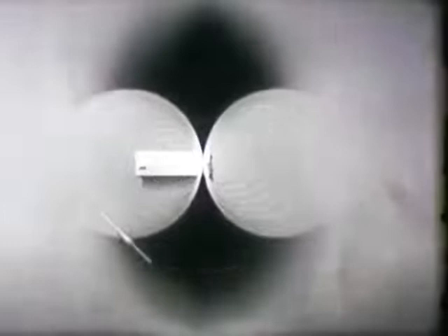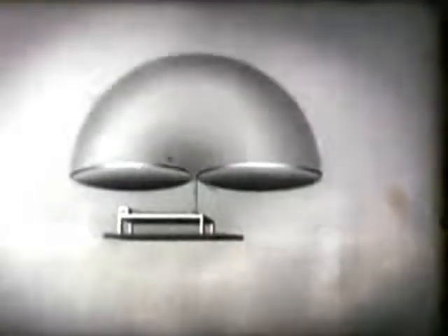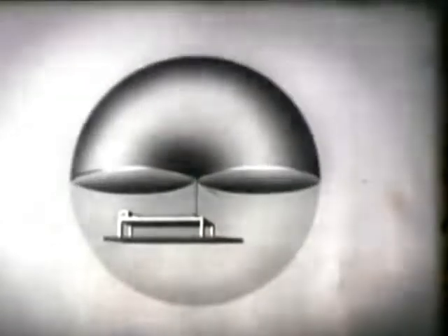Moving the receiving antenna into the radiation field, it will start to pick up signals that increase to maximum strength when the receiving antenna is broadside to the transmitting antenna. By plotting a graph of the signal strength received, we get a cross-sectional view of the radiation pattern. A three-dimensional representation of the pattern looks something like a donut. Regardless of its physical length, any half-wave antenna will radiate this type of pattern.